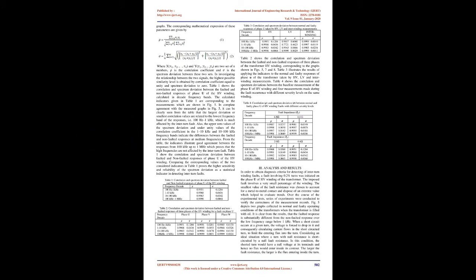Once the appropriate transfer function for fault detection was identified, the next step was to determine the most appropriate combination of terminal connection and measurement type for achieving the maximum fault detection ability. Open and short circuit terminal configuration and three categories of winding measurement including high voltage, low voltage, and inter-winding measurements were made to identify the most sensitive configuration for detecting winding faults.